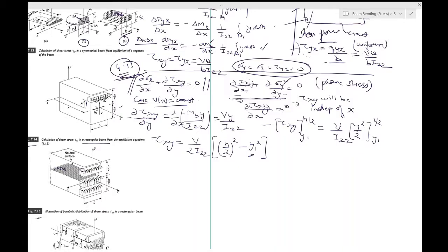We have seen that over there. And obviously tau xy is the same as tau yx at any given point, so the size of the arrows should be the same, like this arrow vertically should be the same as this arrow horizontally. Obviously this arrow over here will be shorter compared to this arrow which will be longest because it's at the maximum, but within one of these small rectangles these will be of the same size.